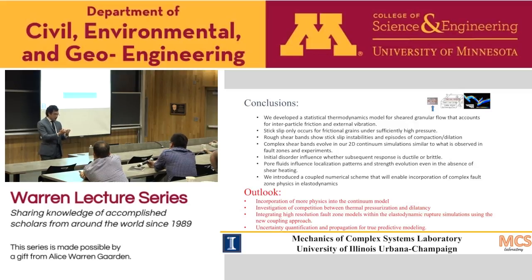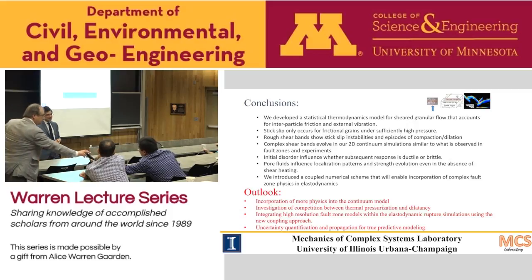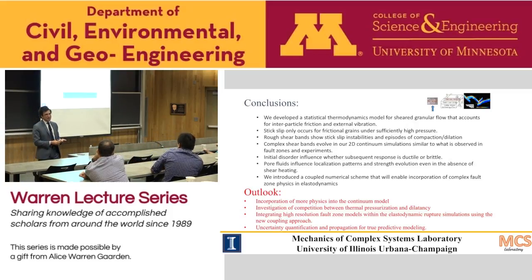So we can think of the disorder being transferred over length scales equal to the grain size by, say, collisions and stuff like this. And for the time scale, we have two time scales that we can use. We have the STZ transition time scale, or the inverse of the inelastic strain rate. So we chose to use that. So the length scale is coming from the grain size, and the time scale for diffusion is coming from the strain rate. But it's a very complicated question in any non-local gradient-based theory. What is the origin of that length scale physically? I know I probably went far over time.